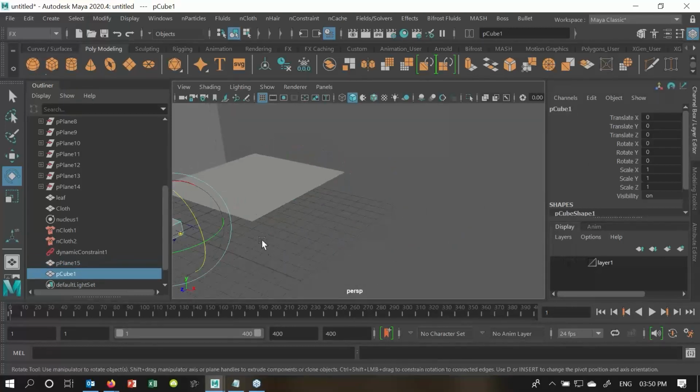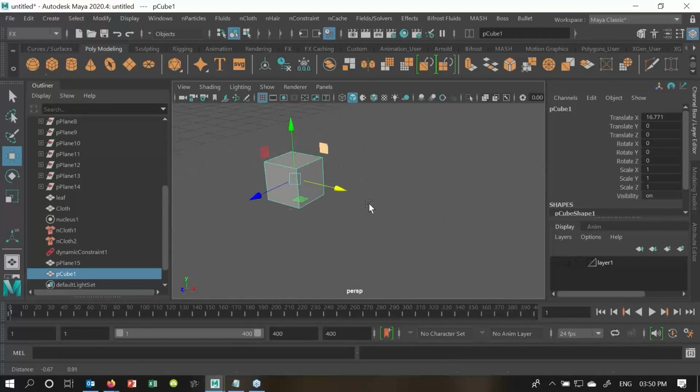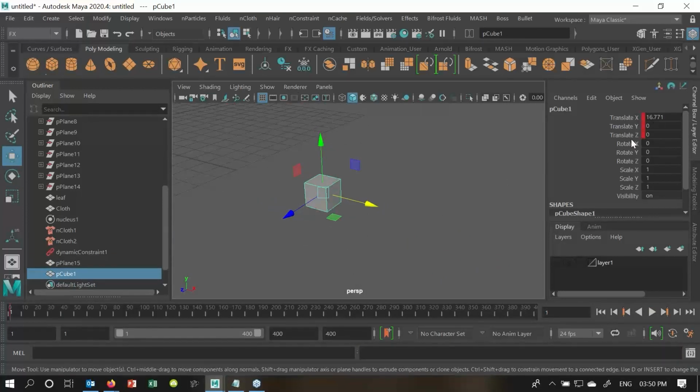First, I'll create one cube over here. Now if I'm doing animation on my character, I'll normally press Shift plus something, or Set Key. If I press Set Key, the key will come to all of my object's attributes. If I press Shift W, only a keyframe for translate. If I press Shift E, then rotation, Shift R, then scale. And if I'm using this, we call them automatic keyframes over here.